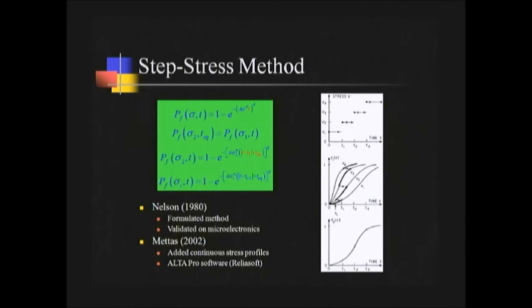And then he substitutes the shorter time into the equation here, the equivalent time, and subtracts the time spent at the first stress level from the total testing time to calculate the time spent at the second or higher stress level. And we can step up multiple times as necessary to cause failure of the restoration, and it gets the testing done in a very efficient manner.